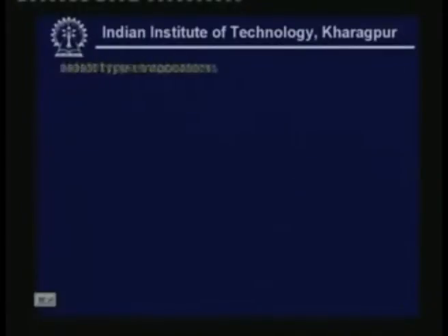As far as the space occupied is concerned, the shell and tube type evaporators occupy much less space compared to other types of evaporators. And the volume is also quite small. That is the reason why the shell and tube type of evaporators are very commonly used in large capacity systems, whereas the tube in tube types of systems, which occupy more space, are generally used in smaller capacity systems. Now let us look at the next type.